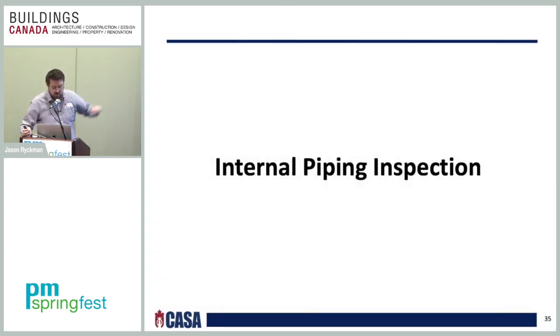So now we're moving on to the confusion. There used to be confusion, back before the 2011 NFPA 25 document, in regards to internal piping inspections versus obstruction investigations. Those are two separate things. The internal piping inspection can be found in Chapter 14. It basically ensures continued operability of the water-based fire protection system by addressing the interior condition of the piping system.